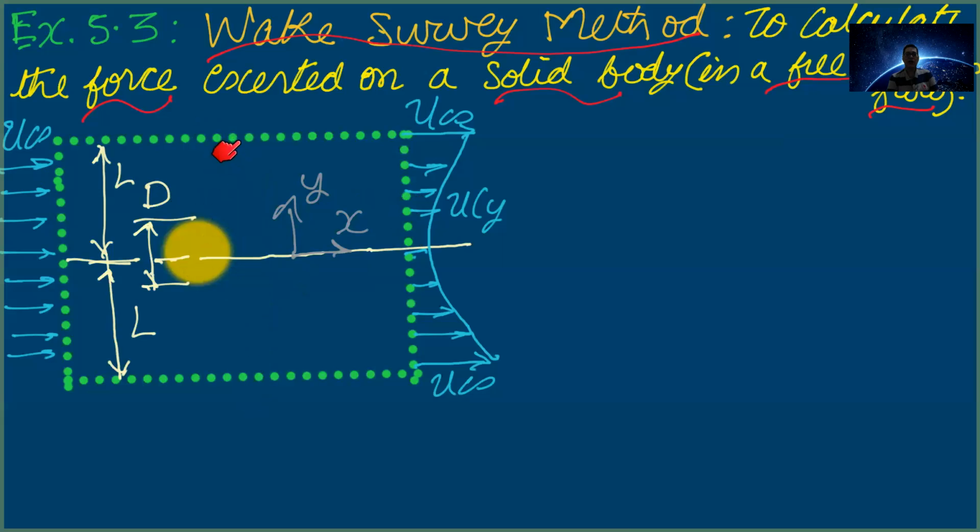So note that mass is entering from the left wall, but it is not only leaving from the right wall, it is also leaving from the top and the bottom walls, which I'll call the side walls. And note that on the side walls, top and bottom, you have a velocity which is u infinity. So to calculate the x momentum flow rate, first we'll calculate the mass flow rate on the side walls, and we'll multiply by this horizontal velocity to calculate the x momentum flow rate leaving from the side walls.